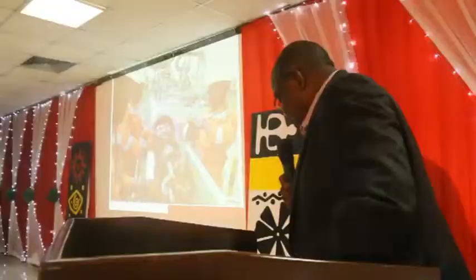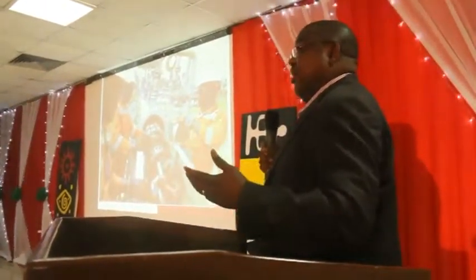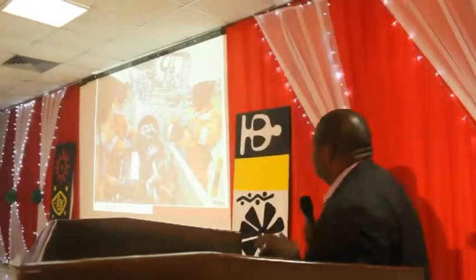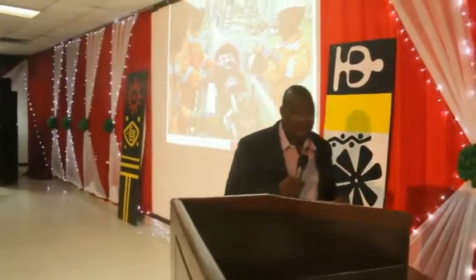Next slide. So intelligent pigging is very essential. Before now we talked about intelligent pigging and said it gives you information, tells you the wall thickness. We just must see some key features on it. The pig will tell you where your problem is, if you have a wall loss, where, at what position. In pipelines, we say 12 o'clock, 9 o'clock, 3 o'clock, 6 o'clock. So where's your problem? And if it is a pipeline of 50 kilometers, where along the line is your problem? You have an odometer that is attached to the pig that will tell you precisely where the problem is, and it also tells you the orientation.